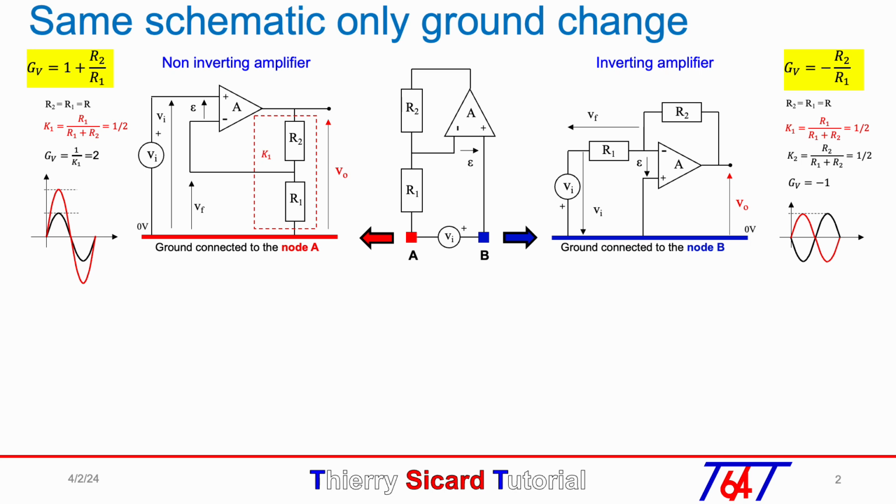It is interesting to see that both schematics we learn in school as two different schematics can be seen as the same global schematic amplifier, just depending on the ground connection to build an inverting or non-inverting amplifier. The open loop amplifier has one pole. We will focus first on the constant gain A times K1 with zero phase between input and output voltage, respectively epsilon and Vout.